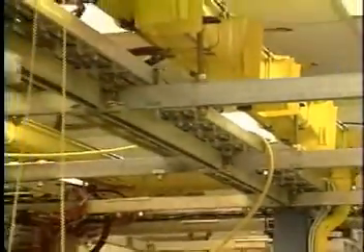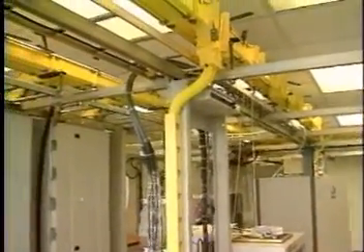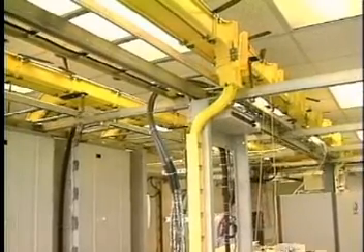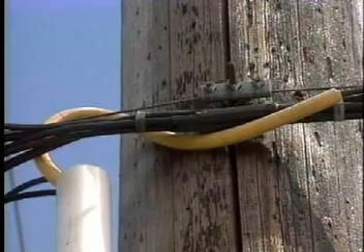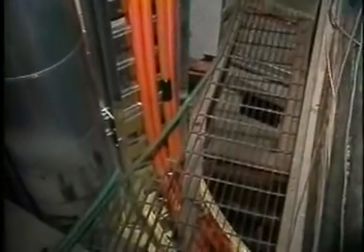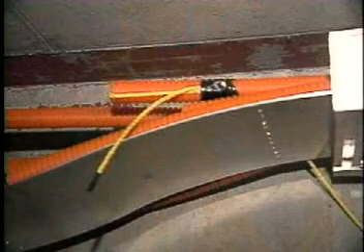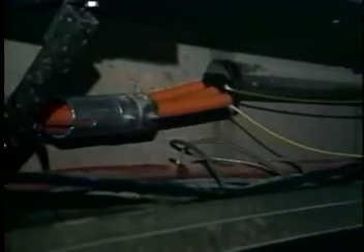When passing from one raceway to another, or when the cable must leave the raceway, a small section of split duct can be placed over the bend and tie-wrapped to a secure fixture to maintain correct bend radius and provide added protection. The use of ducts containing pre-installed pulling rope offers maximum protection for fiber optic cables and ensures the cable will not snag in the raceway during installation. The choice of pre-installed pulling line is cost-effective because it costs less than if purchased and installed separately.